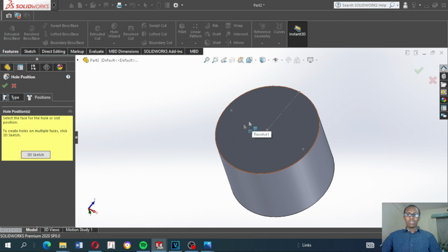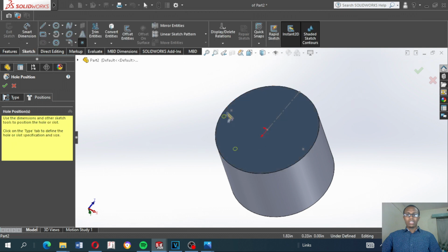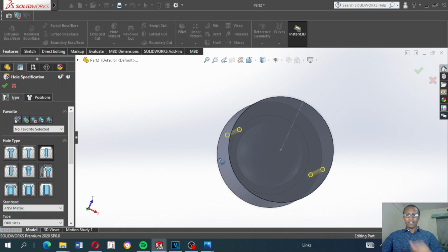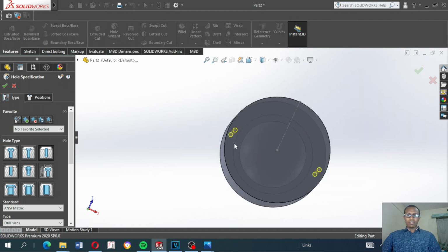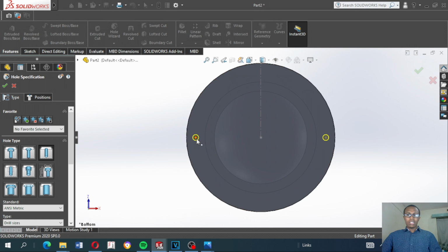On the position option, you'll come and click the bottom of your model. Click the bottom, and then it will give you a preview of the hole. Now you bring your mouse, click on the center where you actually drew your points there. Now you might not notice this, but this is not the size of hole that we need for the slots for our guide pins. The holes need to be a little bit bigger.